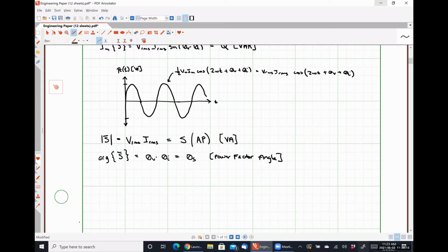You have to be careful about the radius of your bends, because you can break it more easily, or you can cause deformations, which will change the cross section of the wire. If the cross section gets narrower, that portion is going to get a lot hotter because it has more resistance to the current flow, which could potentially burn out your insulation, cause shorts, set fires, all that kind of good stuff.